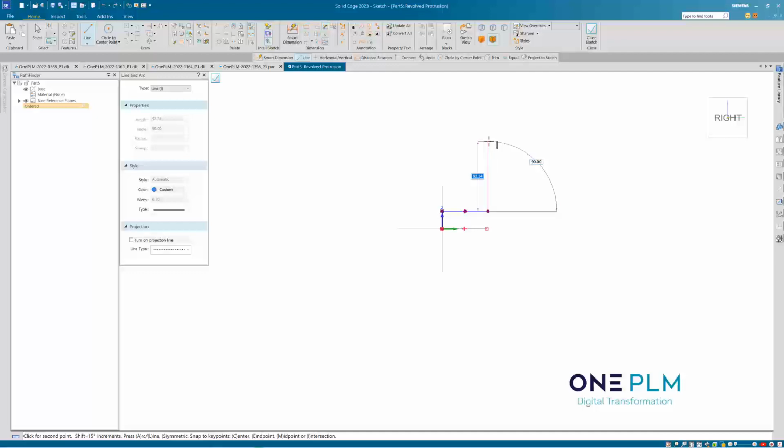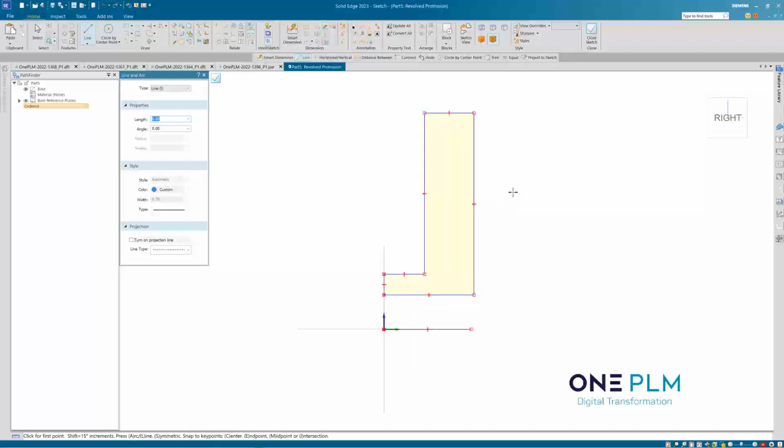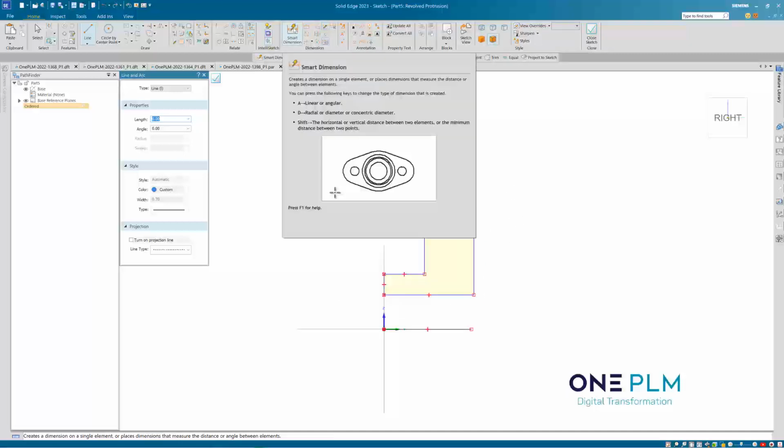I know my overall diameter is going to be about 300, so I'm going to take this to 120, 130. My overall thickness wants to be 40, but I'm just going to drag that so it's roughly 40. Then I'm going to go back down, across, and back to the end point. So that has got my initial feature.